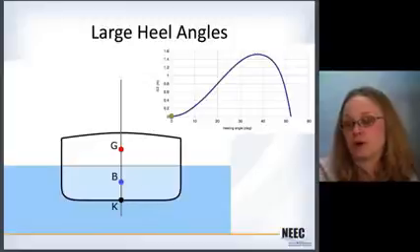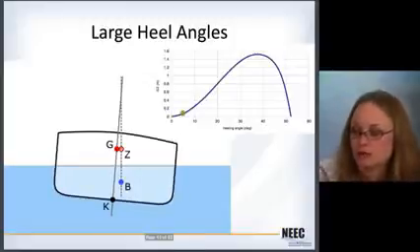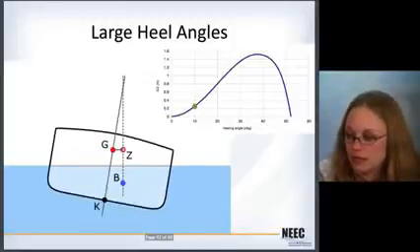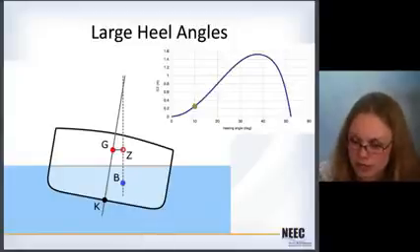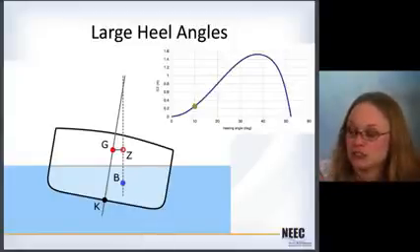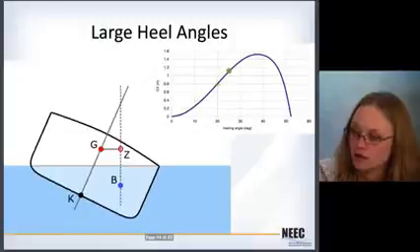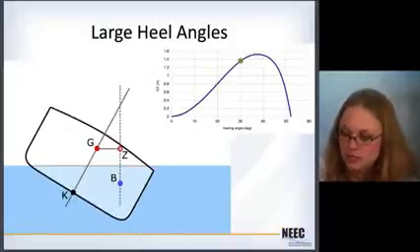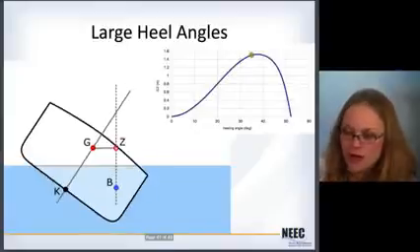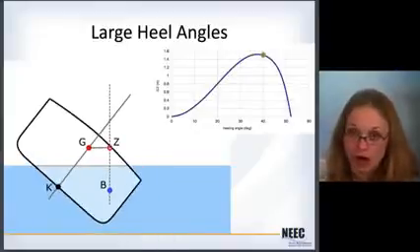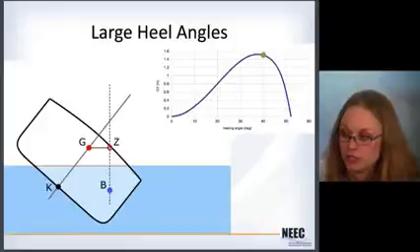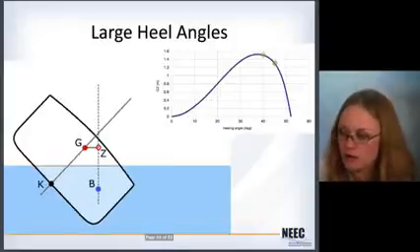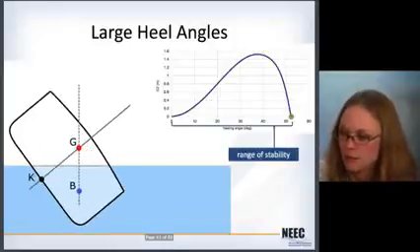So your hydrostatics program will do this. It will take your ship and start to rotate it, and it will calculate all the hydrostatic properties again, and it will calculate GZ for you. And then you can plot it all along this line. You can see how things are changing quite a bit, right? The center of buoyancy is moving way off the center line, and the geometry of the underwater part of the ship has really changed, right? So here the deck has gone underwater.